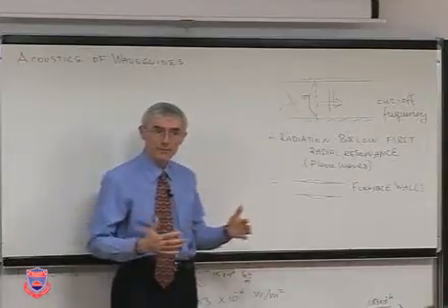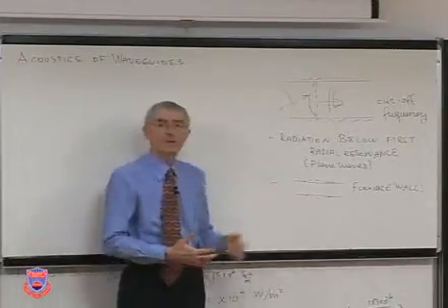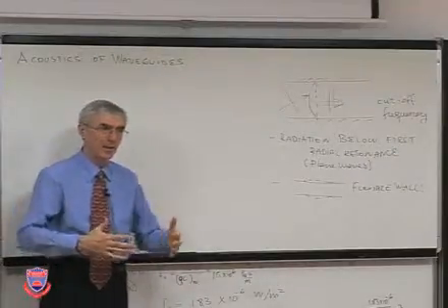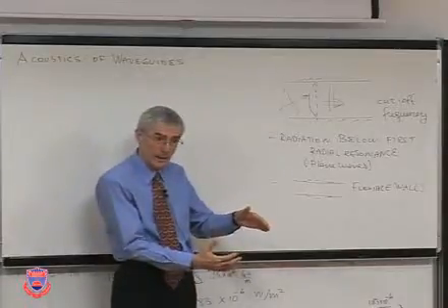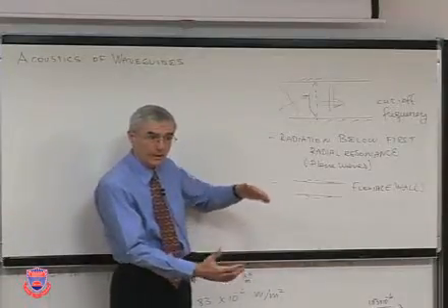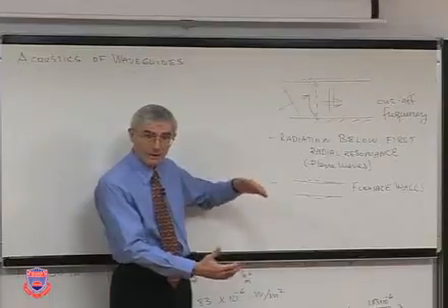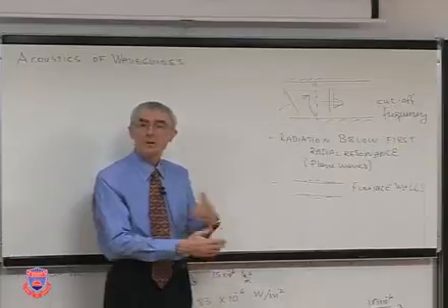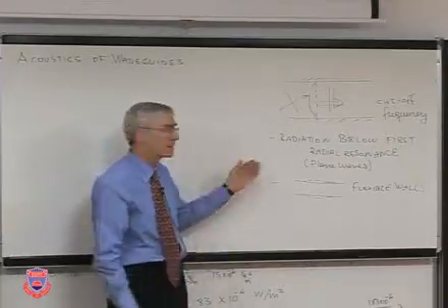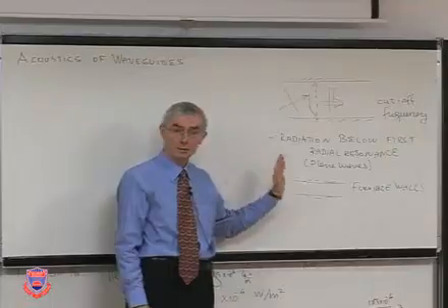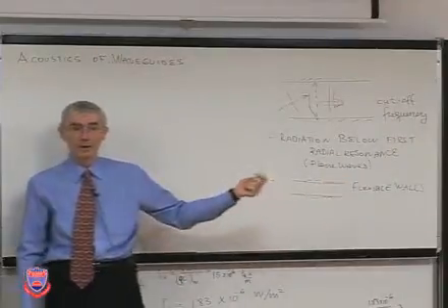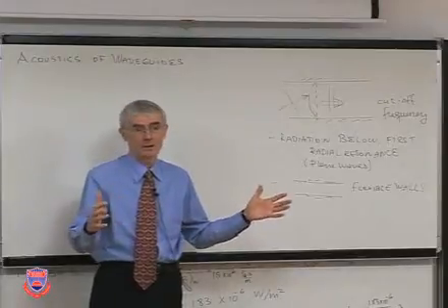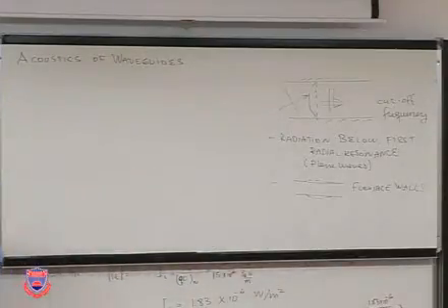Now, how will they flex? Because they have some inertia, some flexibility, it's like an oscillator. And if they flex, what happens? The volume or the area is going to change. If the area is changing, the instantaneous volume changes, density drops. So the pressure equation is going through a transformation through the flexible area. That's what we'll learn. What does it mean? Now, there'll be resonance of the pipe. You hear these sometimes, okay? So that's the flexible walls.